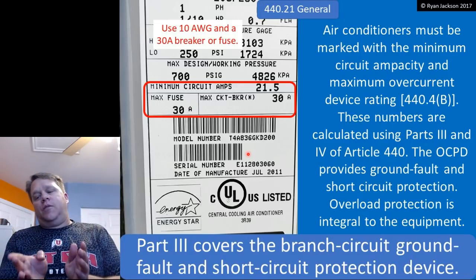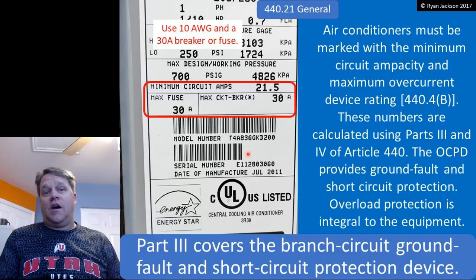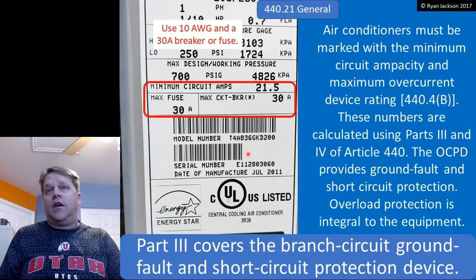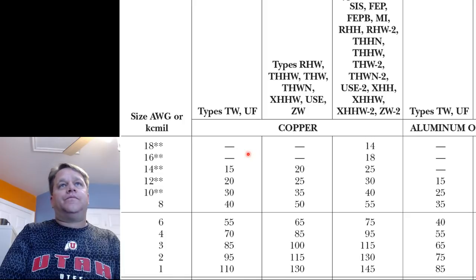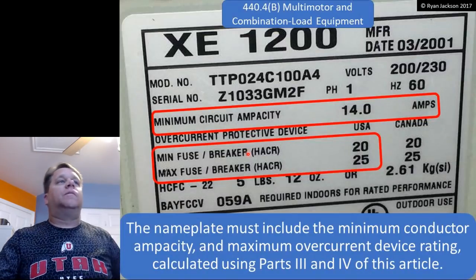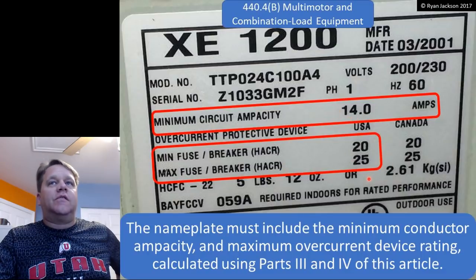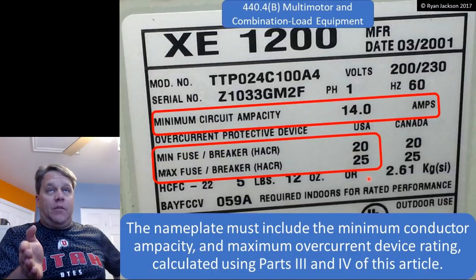Are you comfortable putting 10 gauge wire on a 30 amp breaker? My guess is yes. We've done it thousands of times throughout our career, putting 10 gauge wire on a 30 amp breaker or fuse. Let's keep going and do one more example. Here we've got a unit. Minimum circuit ampacity, 14 amps. Maximum fuse or breaker, 25 amps. Okay. We are going to use a 25 amp breaker.